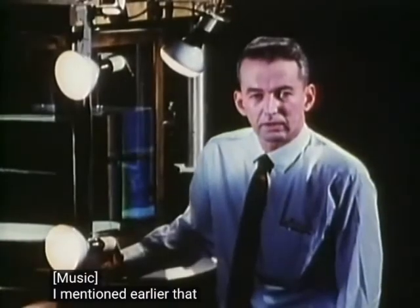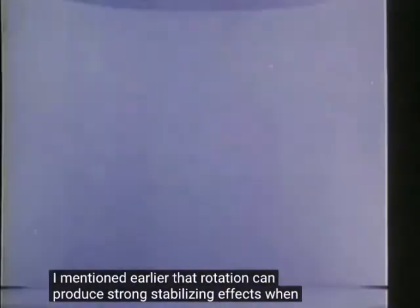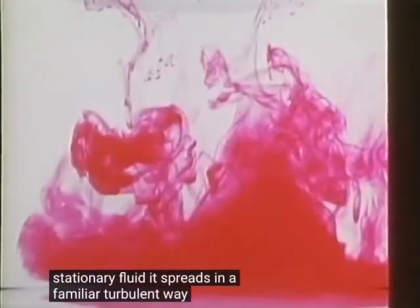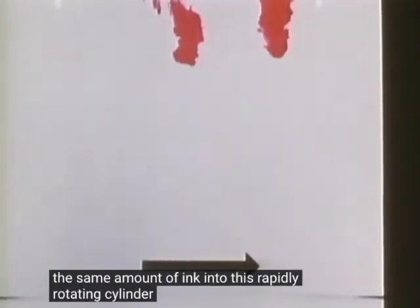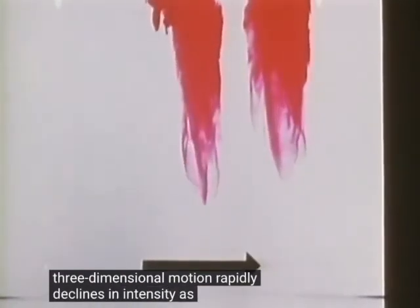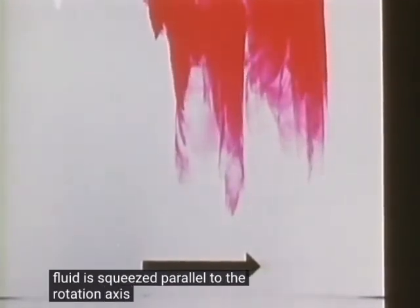I mentioned earlier that rotation can produce strong stabilizing effects. When neutrally buoyant ink is injected into stationary fluid, it spreads in a familiar turbulent way. When we inject the same amount of ink into this rapidly rotating cylinder, the initial vigorous three-dimensional motion rapidly declines in intensity as the marked fluid is squeezed parallel to the rotation axis.